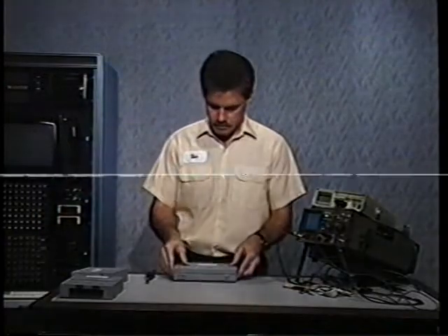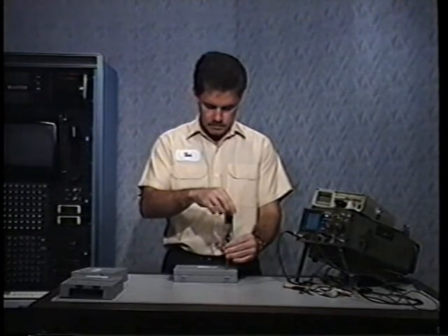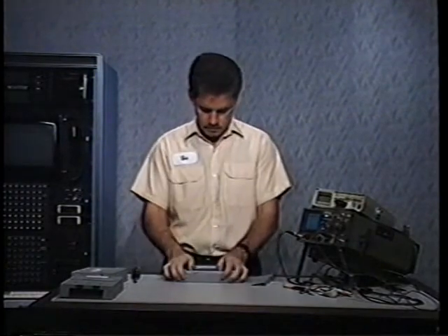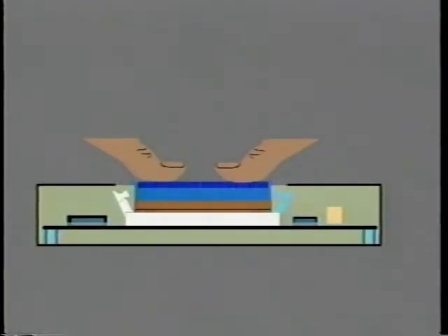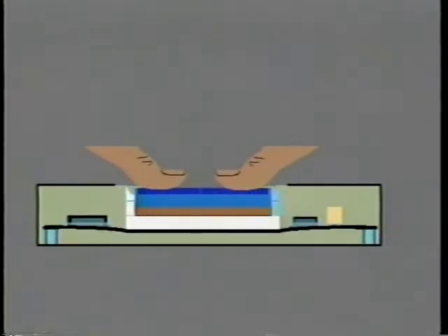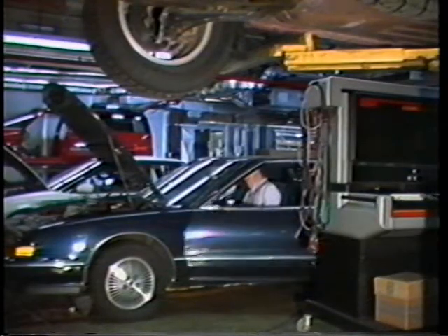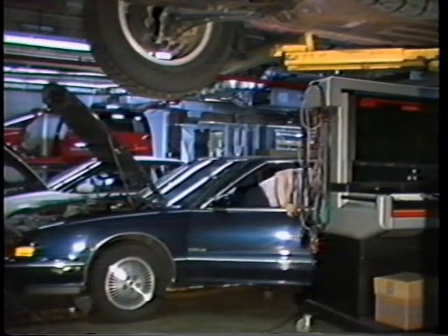It has come to the attention of Delco engineers that many ECMs are damaged when MEM CALs are replaced incorrectly. If excessive force is applied to a MEM CAL during insertion, the circuit board can be damaged. When excessive force is applied to the MEM CAL, the circuit board may flex, causing microscopic damage to the circuit board connectors. When a vehicle continues to run poorly after a MEM CAL change, many technicians think the ECM was bad before the MEM CAL change. In reality, the MEM CAL was damaged by rough handling.